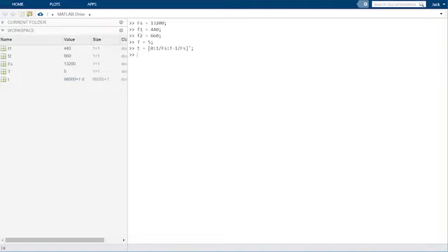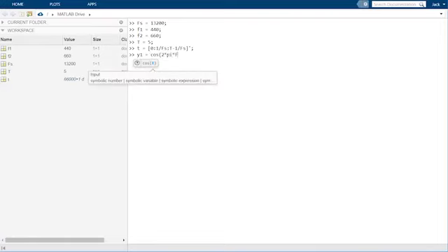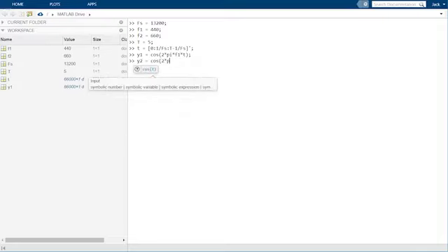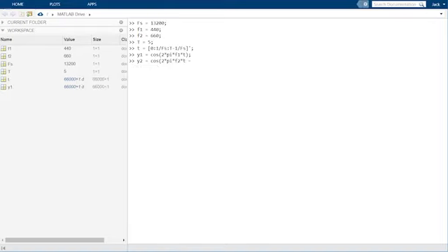Then we can define our cosine signals. First, y1, which is a cosine with frequency f1 equal to 440 Hertz. Then y2, which is a cosine with frequency 660 Hertz. We also add a phase to this cosine of pi over 4 radians so that we have a phase shifted 660 Hertz cosine.